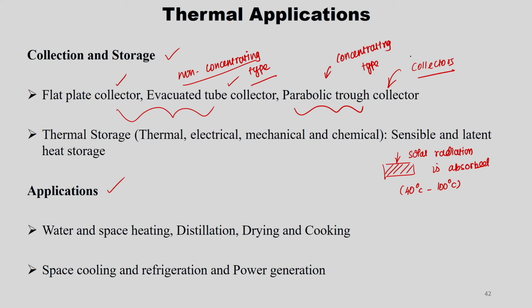There are special arrangements to insulate them to avoid heat loss, and glass covers to trap the solar radiation. We will see that in detail in the 4th and 5th lectures of the second week; here we are just introducing. The difference between FPC and ETC is that, to avoid convection losses, we create a vacuum inside the tube.